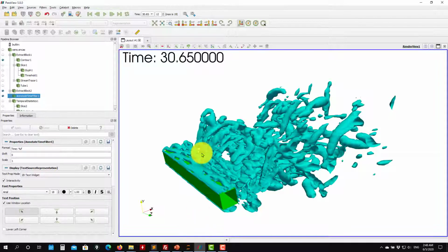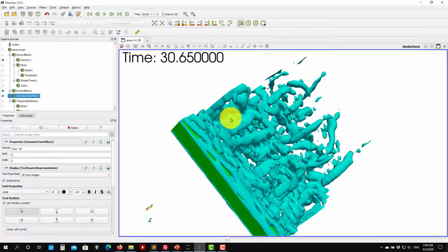And I think this was a crash introduction into Paraview, so from Fluent to Paraview. So my advice: save the format. You can do pretty much the same using Fluent format or Tecplot or CGNS, but I found that Ensight is very fast. It's lighter than the other formats. Okay, so use that, save with the given frequency that we did.